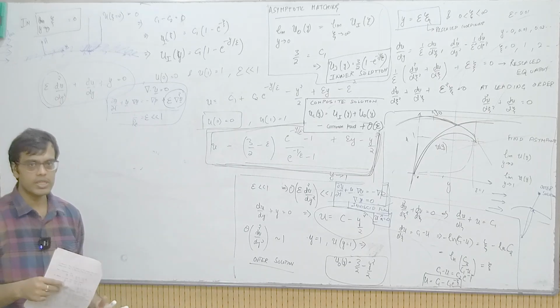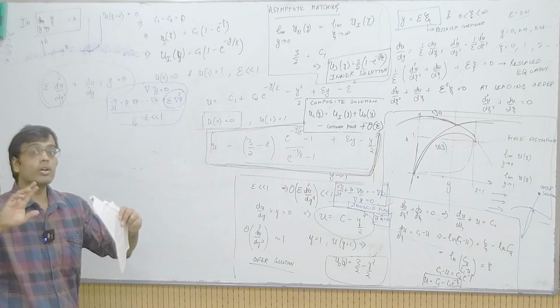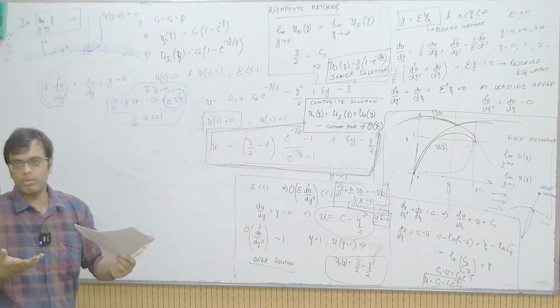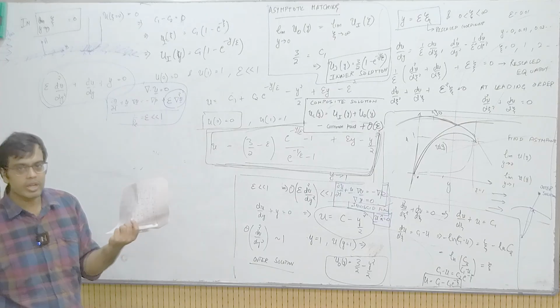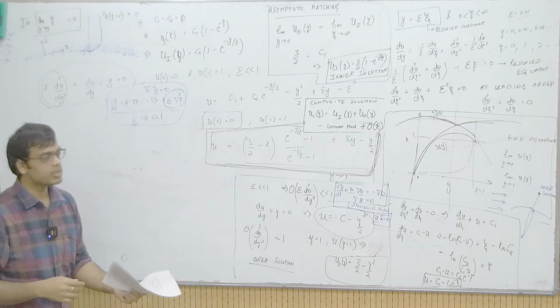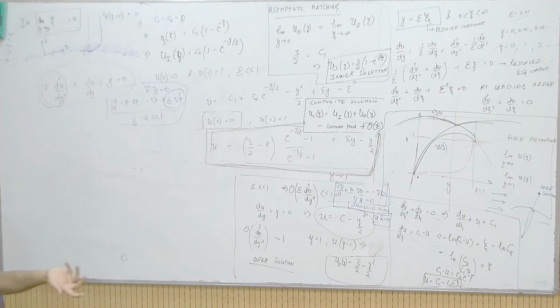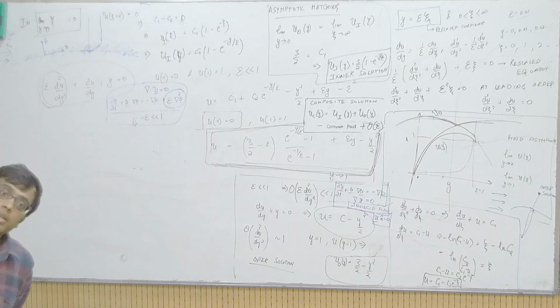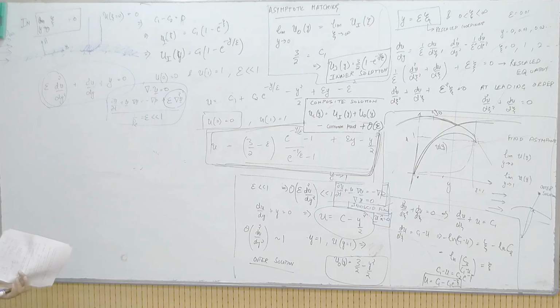So it is not right to say that we did not account for boundary layer in the low Reynolds number flow regime. There's no concept of boundary layer there. There's no distinction between a boundary layer and a non-boundary layer flow there, because these asymptotics don't apply. They are actually reversed. You have 1 by Re, which is very large instead of being very small. So in a way, the non-dimensional equation is showing you that the most dominant effects are actually viscous effects. Does that clarify?